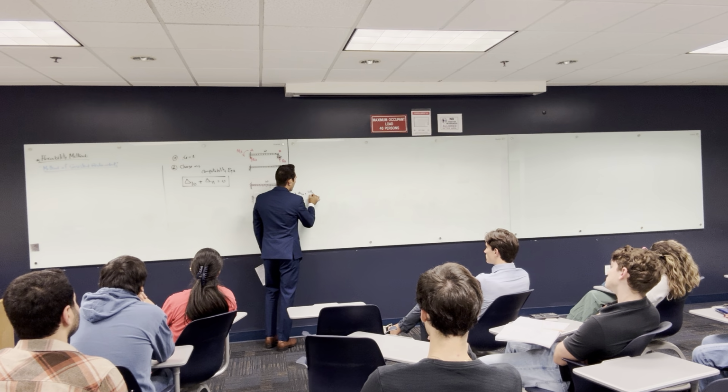So what if you have multiple? This is only one reaction. Let's say that my beam is something like this. I have a hinge here, one roller here, and one roller here, 2, 3. How many redundants do I have in this problem? 3, right?